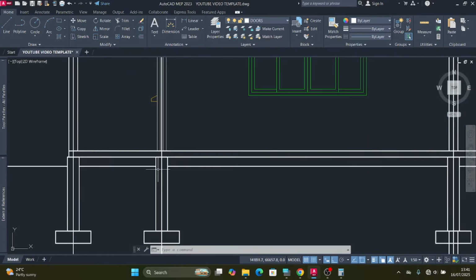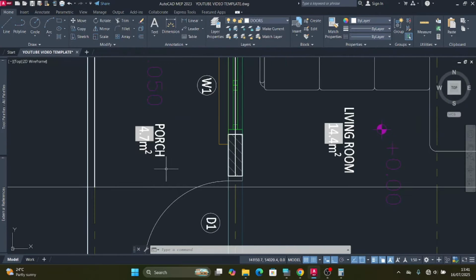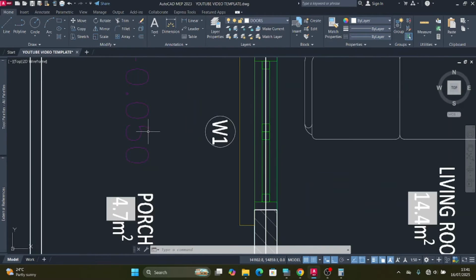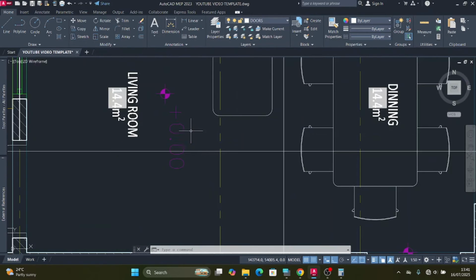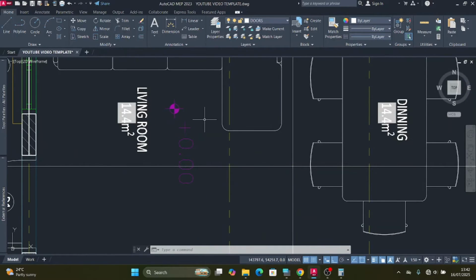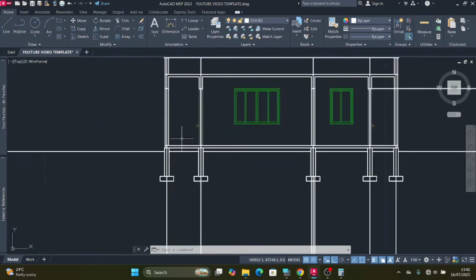Then next, according to our floor plan, you can see that this floor over here at the porch, it's offset 50 millimeters below this floor that is inside the structure, like at this point where I indicated living room. Alright, so we want to include this right here.